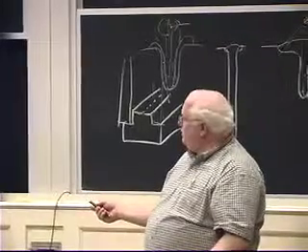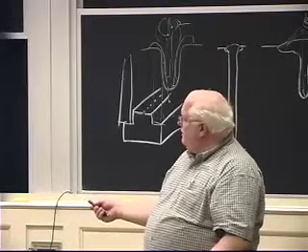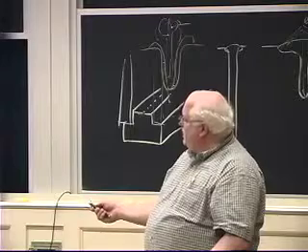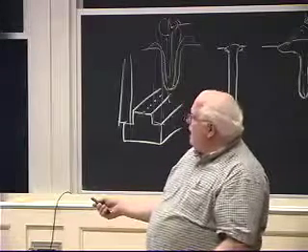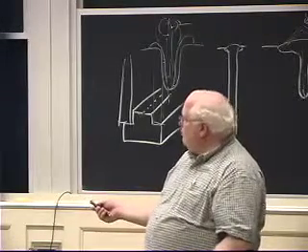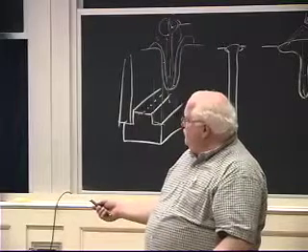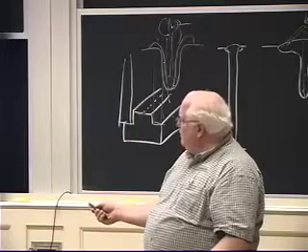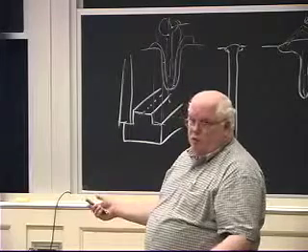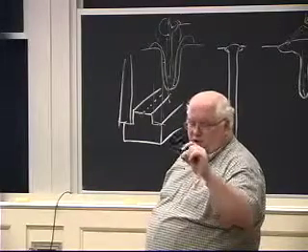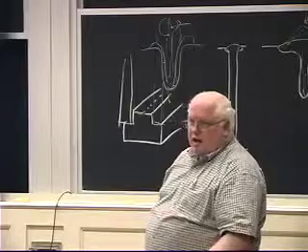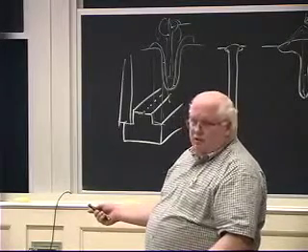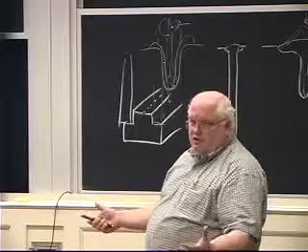With lower currents, you can get a better focus to your beam, which we'll talk about tomorrow. But if you want to go to higher powers and higher currents, you usually don't want to go above about a half an amp. So you're limited to 50 kilowatts if you're using a half an amp at 100 keV, but at 40 keV you'd be limited to 20 kilowatts, and 20 kilowatts is probably going to limit you to maybe half an inch thick material. If you really want to do thick section electron beam, you have to go to these higher voltages, but then you have the extra cost of X-ray shielding.